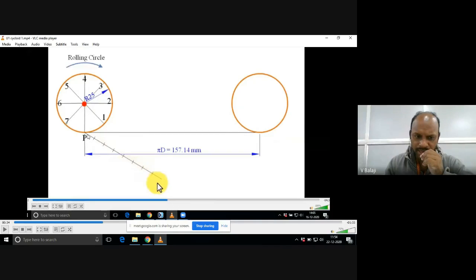On this angular line, I am repeating again. This angle can be any angle, 0 to 90 degrees, any angle you can take. This length can also be any length, but while cutting the arcs, you can set one fixed radius, any radius, but set one fixed radius. From point P, you draw one arc, and from that arc, you draw one more arc, like that. The distance between any two arcs must be the same.